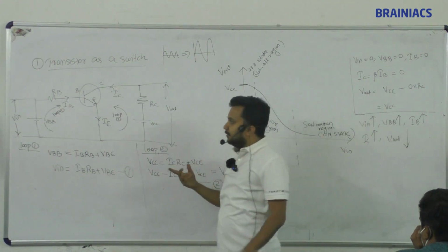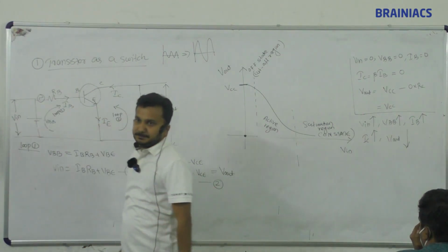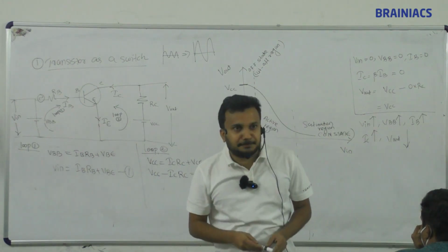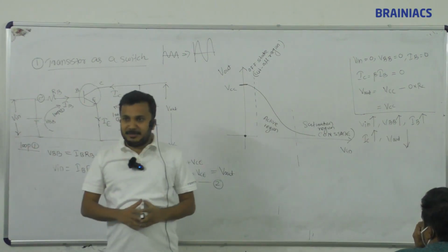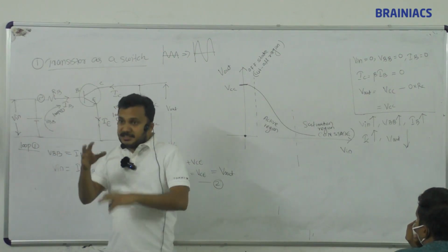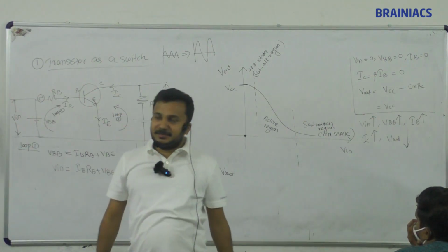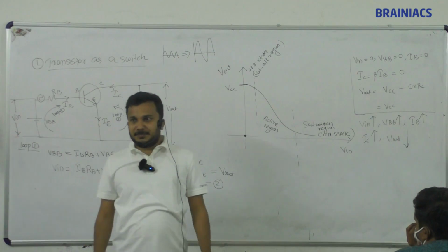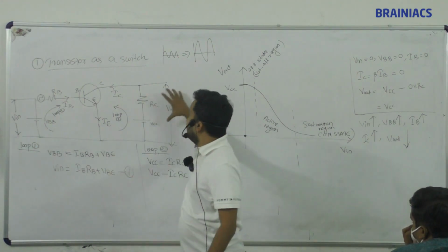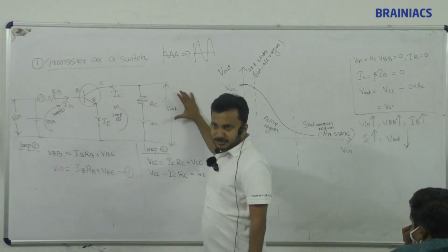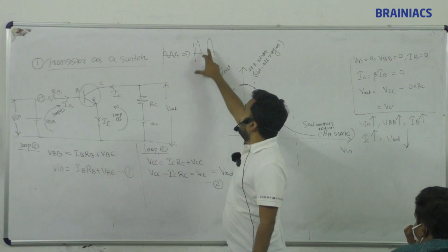So in addition to the battery, I will connect a sine signal here. What actually am I doing here? I am not converting anything. Already one DC signal will be here, this DC battery. Then additionally I am giving an AC signal also. So what is actually happening? Addition of two signals, AC signal plus DC signal. I am giving a small signal, but at the transistor output, if I keep an oscilloscope, that instrument, outside, I want this size of signal.